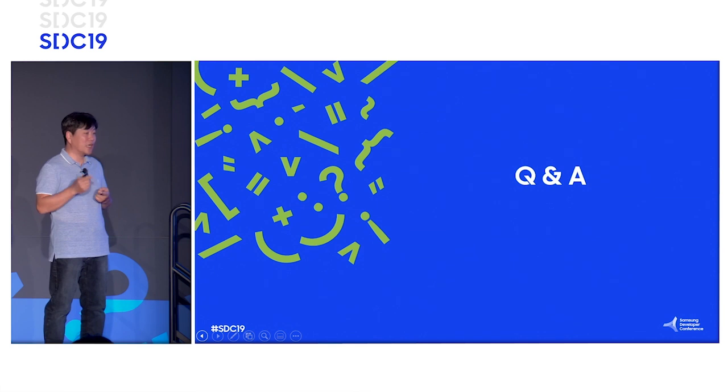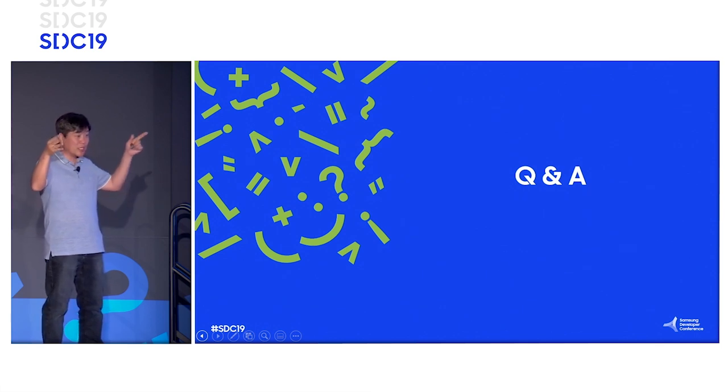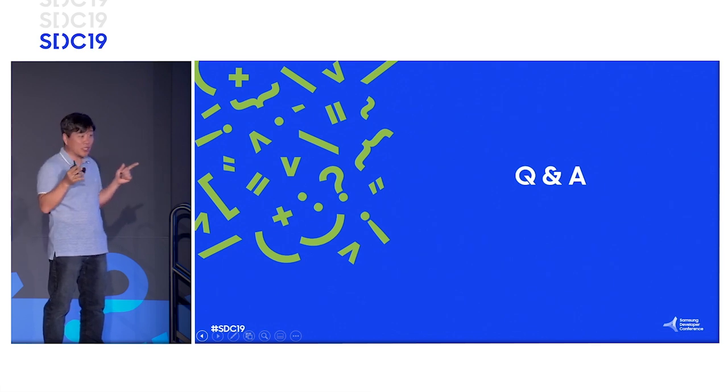So how you divide the scene, that's a very important one. For example, the transition: if you have 10 frames or 100 frames, that's a scene. But for example, for a smooth transition, you can divide that into multiple scenes, or you can treat the entire transition as one scene, because you're applying only one statistic information and one curve over the entire transition time. You don't have any artifact.